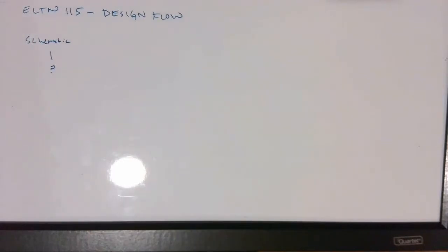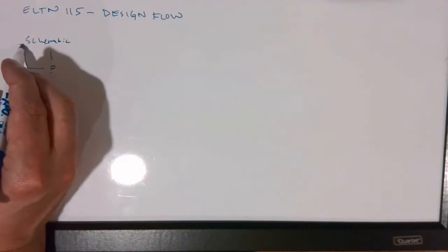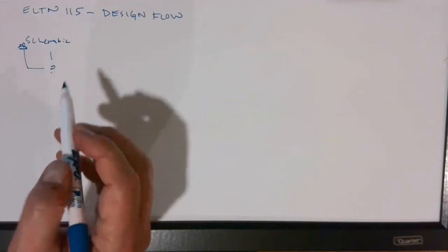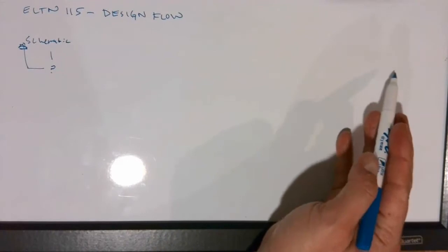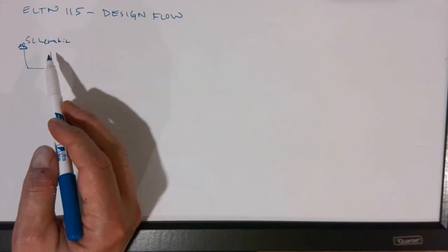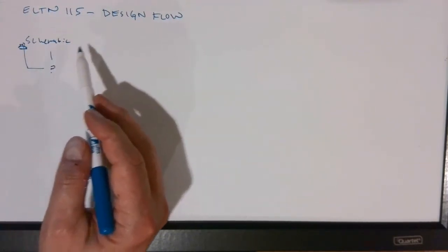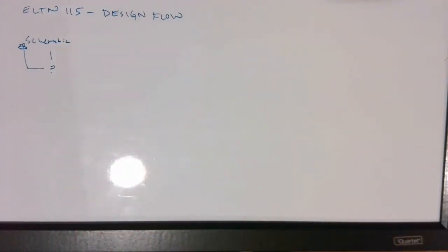You've got to visually check it compared to the original schematic you're working on. And so you're going to go back through this process a few times until you check and make sure everything's correct. One of the points that's super important with this is there's a lot of process steps before we actually get the circuit board manufactured. If you have a mistake in your schematic, you could have a circuit board that looks beautiful when it's done, but if that error exists in the very beginning, it's going to propagate all the way through. So quality assurance or quality control is super important all the way through the circuit board design process.